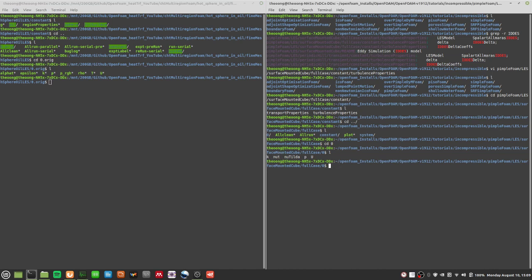So that will actually store, because usually in turbulence we model our turbulence as an artificial increase in viscosity, and the velocity fields we actually resolve are the average velocities, not the instantaneous velocities. So to calculate nu T, we will need k, which is the turbulent kinetic energy. We also need omega, which is the turbulent frequency. That's why we are using that. And of course, for the heat transfer portion, we will need alpha T. That again is calculated through our turbulent Prandtl number.